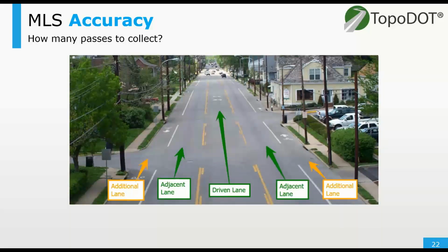But in some cases, it's just a matter of strategy to capture as much as possible within one pass. So here we can see the drive lane has been shifted over into the shared lane to get the entire roadway here. So if that's possible, great. But for larger corridors, you're going to have to collect more passes, and you'll just be keeping them separate during the analysis phase. For example, highways have barriers, so a single pass per bound might be sufficient.